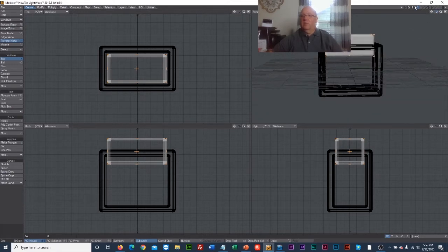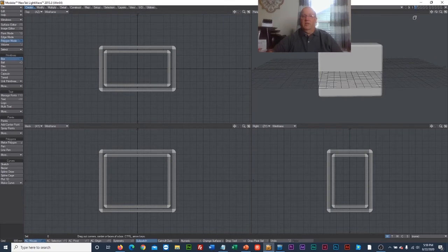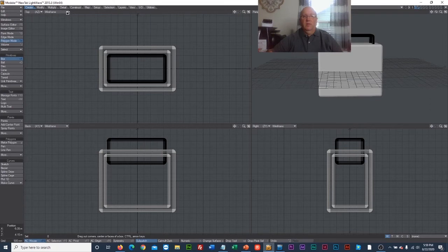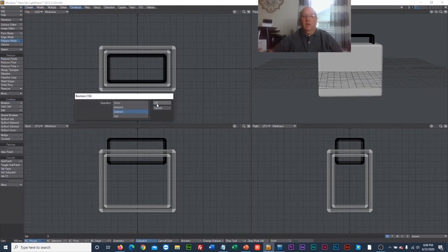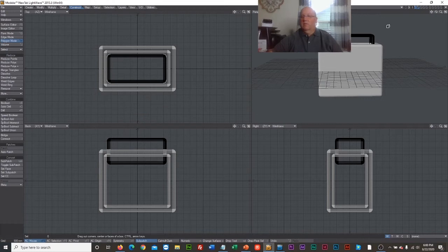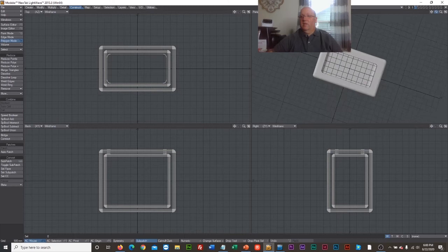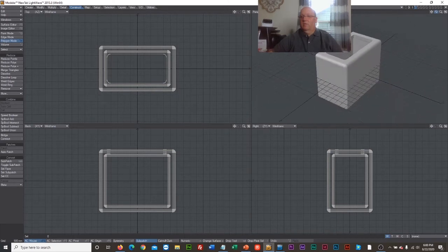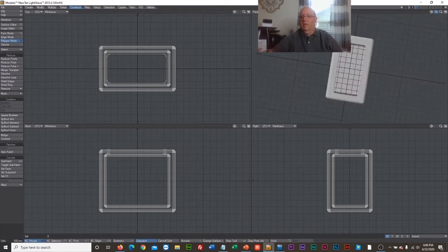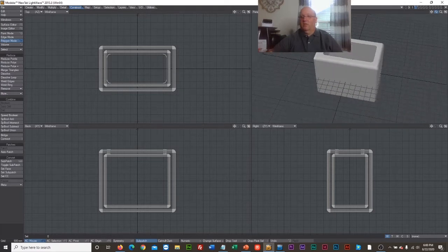And so then I'm going to put my big box in the foreground and put that box in the background. I'm going to go here. I'm going to go to Boolean, subtract, boom. So then if I look only at this, I can see, and it appears to have worked. It's not perfect, but it's there. I now have a box that has an internal shape.